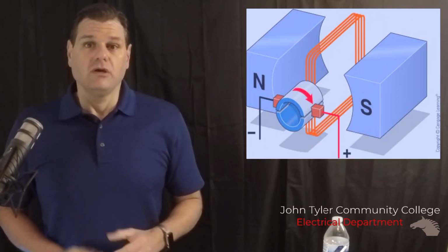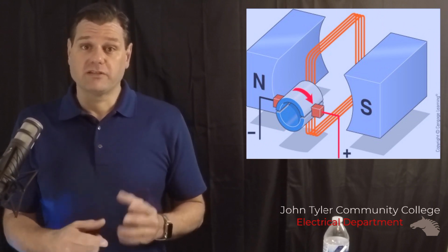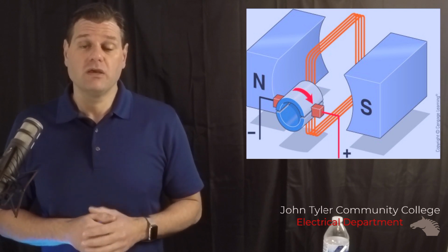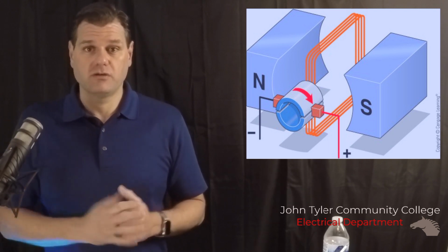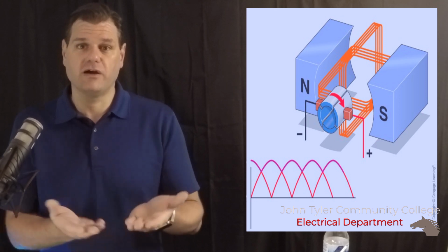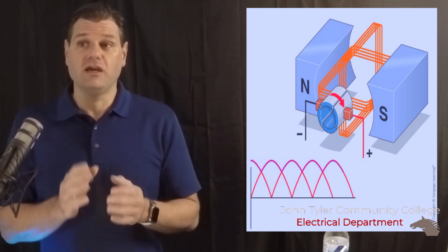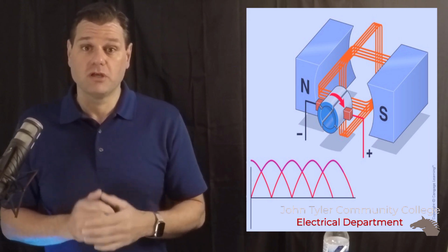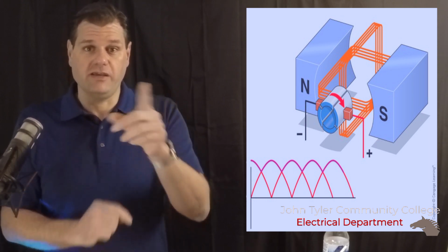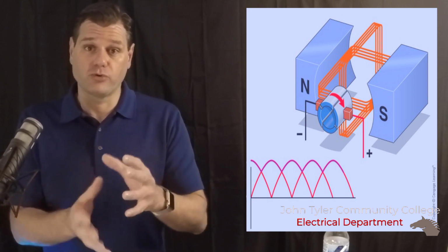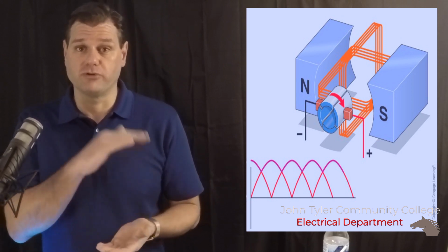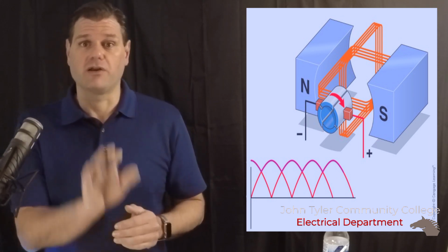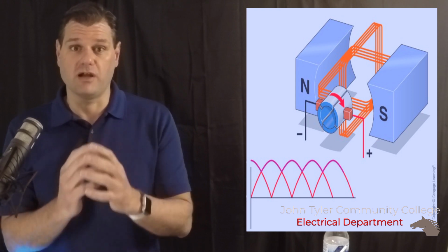So what we do, by simply adding more wraps, more windings, we have more conductors cutting through the flux, increasing our voltage, right? Now we want to take out that lurching motion, so we go ahead and cut our commutator in half once again, and now we have 4 winding sets that are actually going through these poles. So at any one point, you always have a coil going through the magnetic field, causing it to always produce a voltage. So you're going to get these little ripples versus on and off, less lurching, right? So it's going to be a constant flow of electrons.